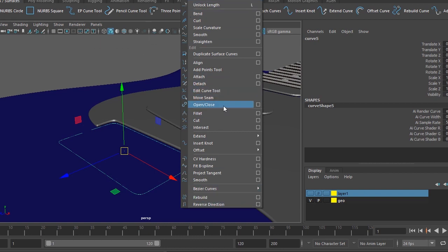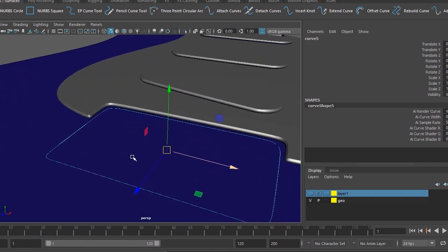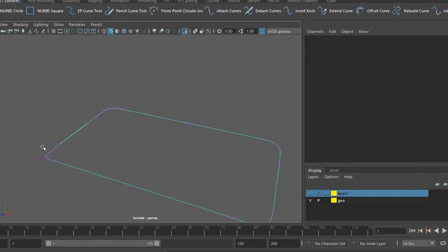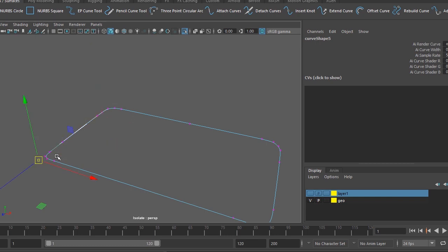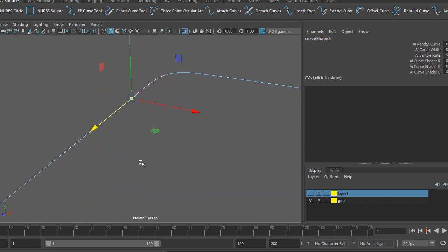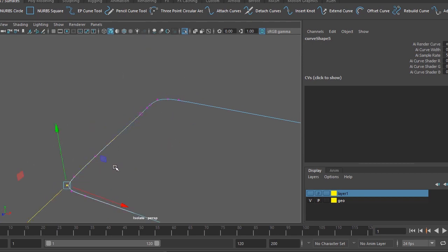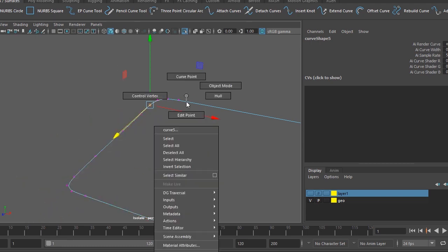Curves open, yeah, open close curve, and this curve has got some overlapping problem that I could identify because I could see the curve is thick. So I'm selecting a vertex using left and right arrows, and then I'm start moving this point by point, so they should jump sequentially. So yeah, I've got this.